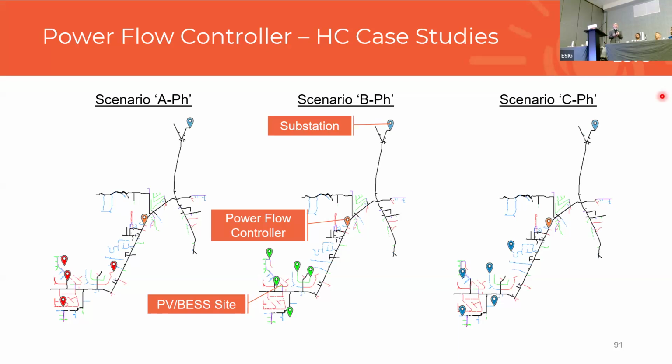So if we think about that EPRI paper, one, you have leveraged more of your system by eliminating some of that imbalance, so your unconstrained region of your system has just gotten larger. But similarly, you are also optimizing your volt-var region or your voltage control region. So now your unconstrained region got larger, but so did your voltage region, where you can do a little bit more by consuming less reactive power because that highest voltage isn't really there. So it can help both three-phase DER in that perspective, as well as single phase, which is what we demonstrated on this slide.